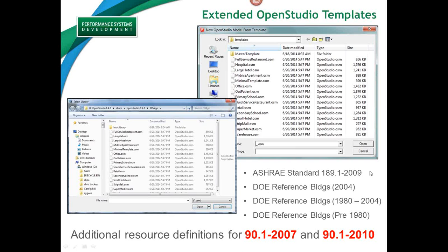So essentially what we have with this feature is we've taken the classic paper version of ASHRAE 90.1, 2007, the tables that are included, for example, Table 5, which has different climate-specific tables of minimum compliance performance specifications for envelope, forming fabrics, roof, walls, above grade, below grade, and so forth. All of that knowledge has been taken and transformed into OpenStudio objects that can be very easily applied, very easily attributed to building form and fabric.